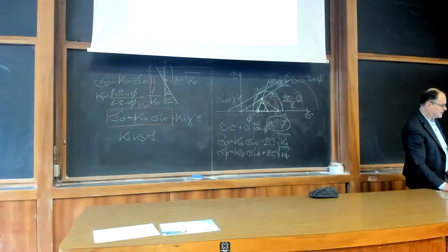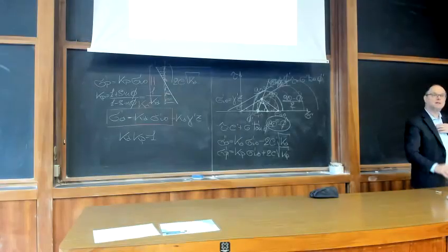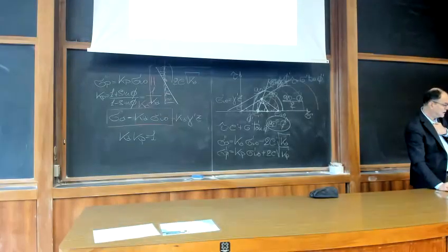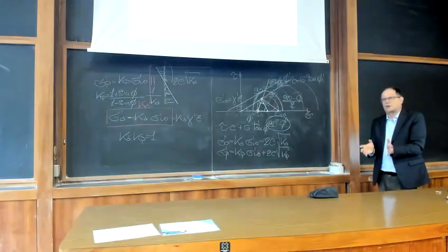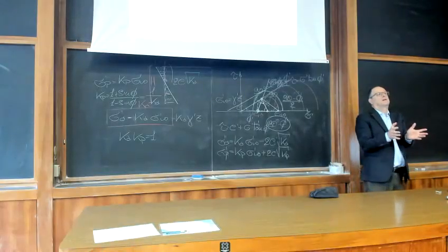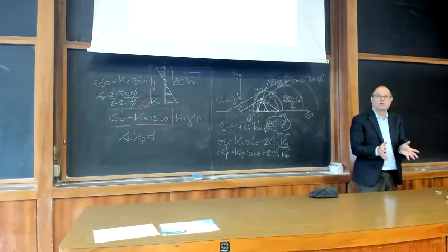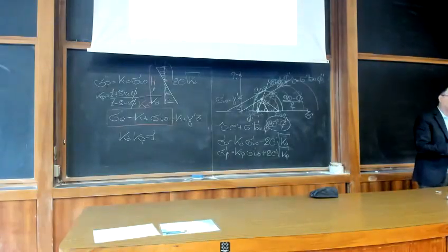Now, if you look at this possible applied load settlement curve, this means that I have to stay away from the bearing limit, but I have to guarantee that under the working load, the resulting actual settlement, which as I said will never be zero unless the soil is perfectly rigid, is small enough, is tolerable for the structure. This is a bit more tricky to define, because what is tolerable?